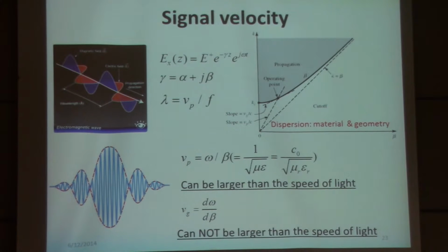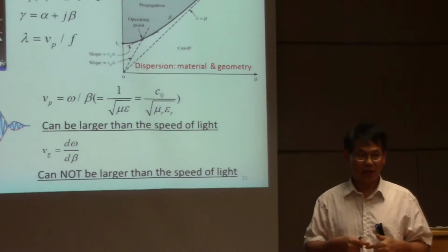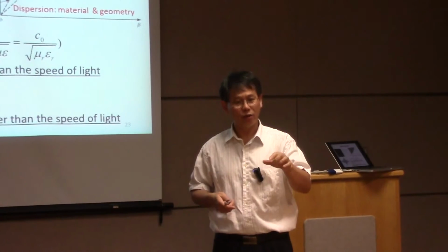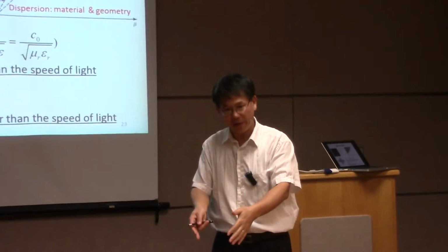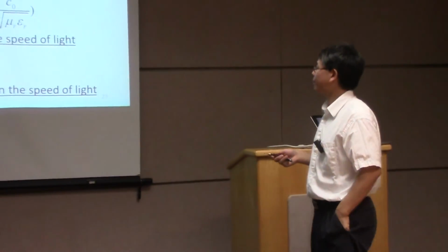So two speeds, and you see the speeds are different at different frequencies now. Okay, that difference comes from the materials, which may depend upon frequency, right? At different frequencies, the materials respond differently. Or it comes from something called geometry dispersion. So it depends upon how you lay out and draw your line, how wide, how narrow. They will give you different frequency responses, okay?